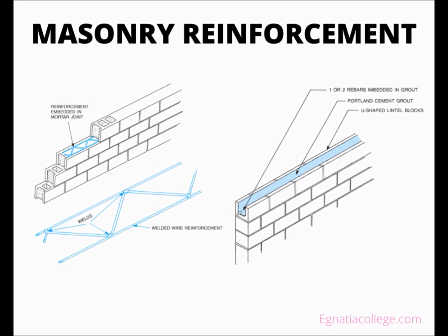Greater strength can be achieved by building the masonry wall with reinforcement bars in the cores of the masonry units, then filling those cores with concrete. Concrete used for this purpose is called grout. Reinforcing steel is also embedded in masonry walls to tie structural elements together. For example, it is quite common for rebars to protrude out of the foundation and into the exterior masonry walls.